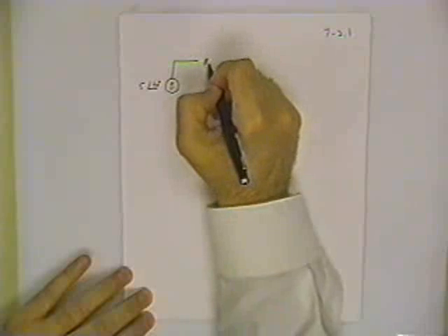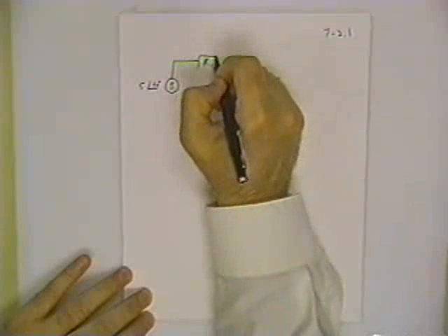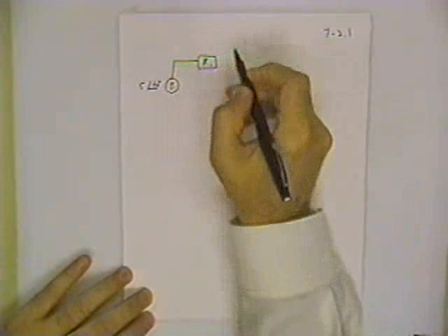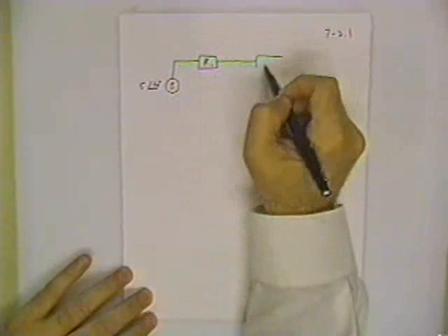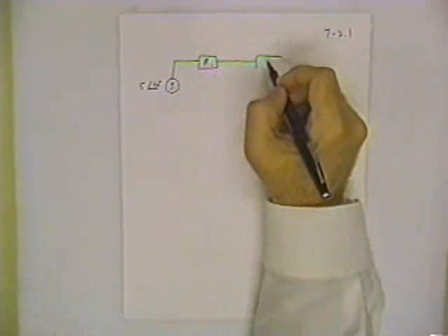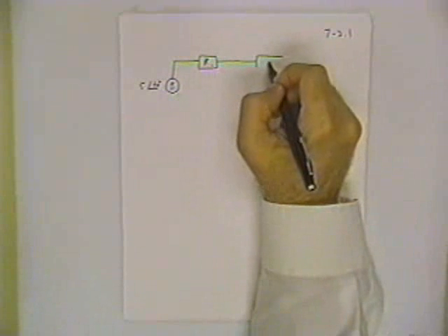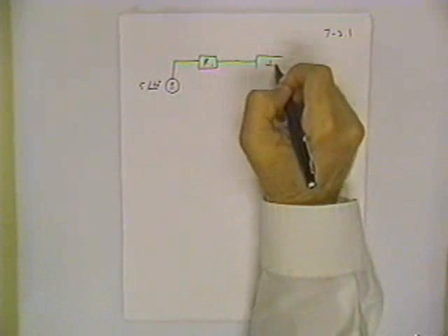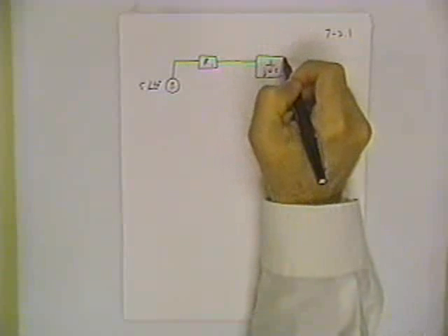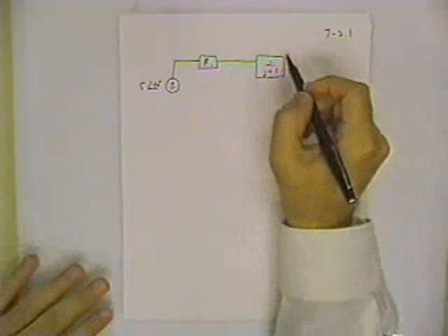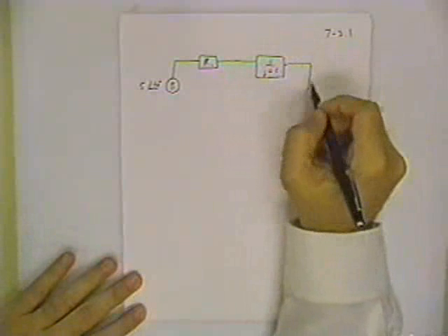Okay? And you have R1 as a numerical value of the resistance. That becomes the impedance for that resistor R1. For C1, we're going to put in the pure imaginary number, 1 over J omega C1. And so on around the circuit.